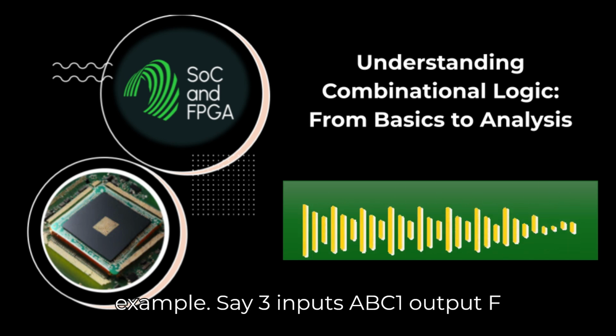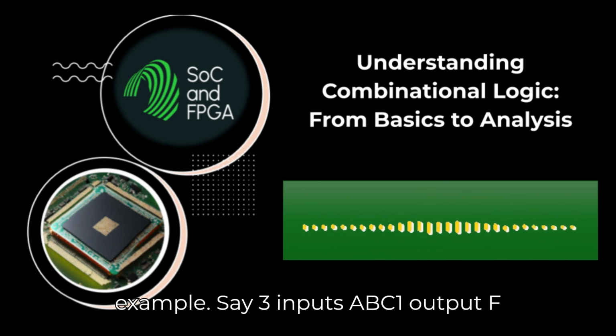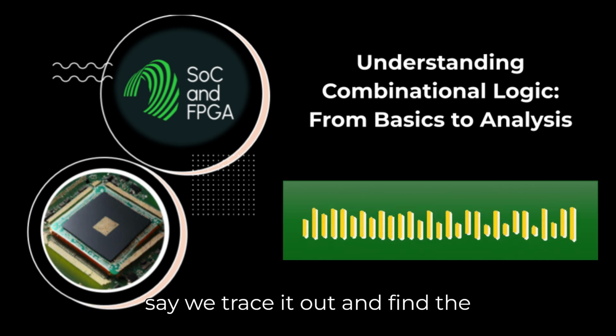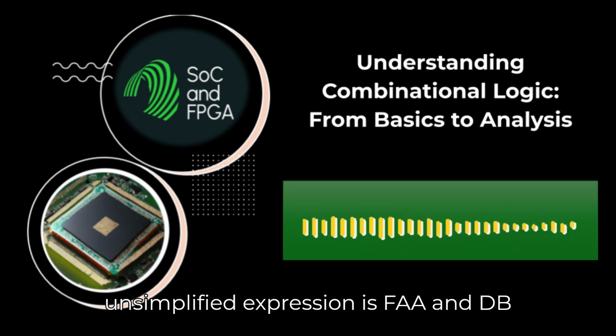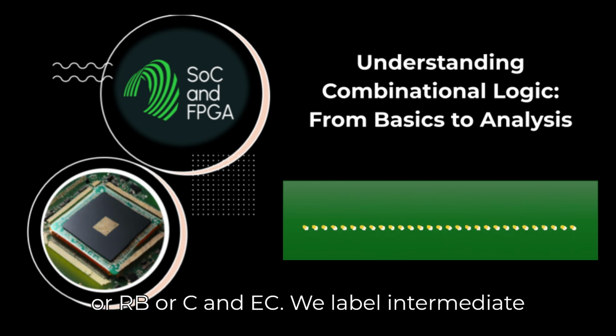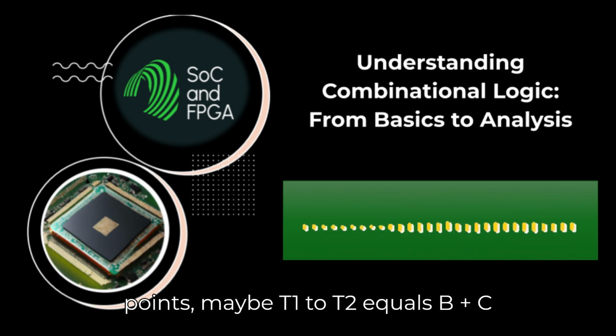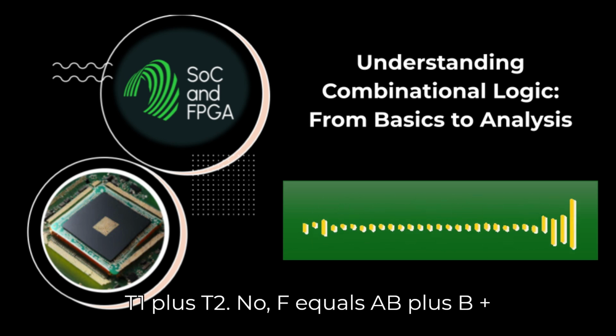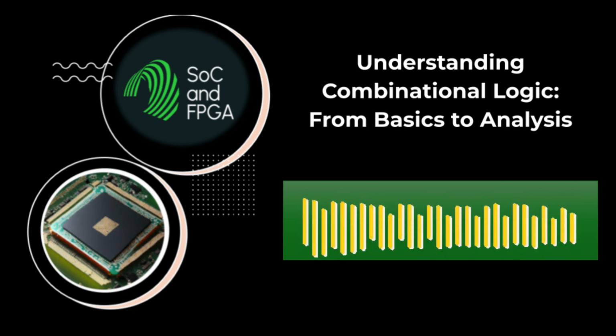Let's try a quick example, say 3 inputs A, B, C, 1 output F, maybe some ANDs and ORs jumbled together. Okay. Steps 1 and 2. Let's say we trace it out and find the unsimplified expression is F = (A AND B) OR (B OR C) AND C. We label intermediate points, maybe T1, T2 equals B plus C, T3 equals T2 AND C. So F equals T1 plus T3. F equals AB plus (B plus C)C.